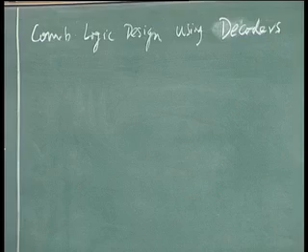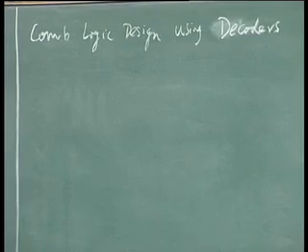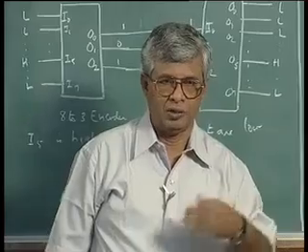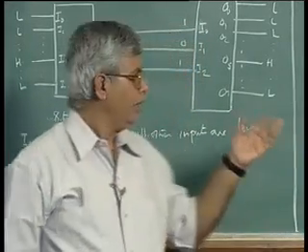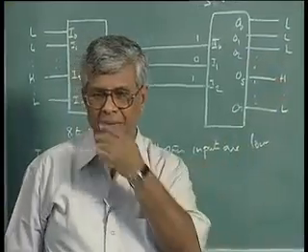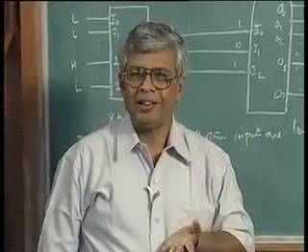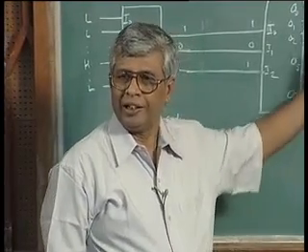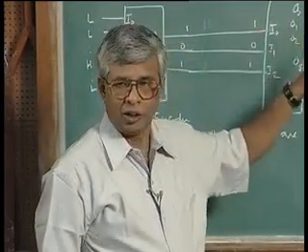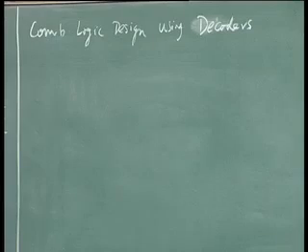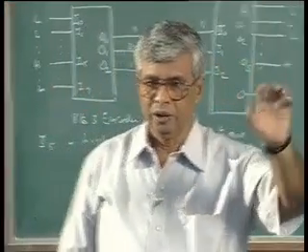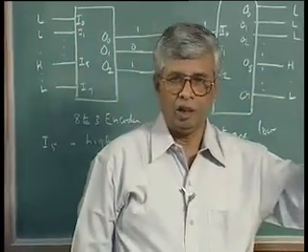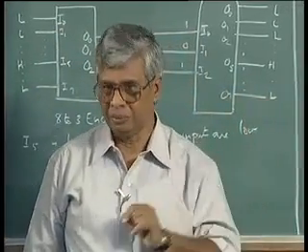This is a very straightforward procedure here, because with the multiplexer of course the mapping procedure was very clear, but not even that here, it is a straightforward case, because when you have 3 inputs and 8 possibilities, this is similar to the truth table, is it not? So that means all possible minterms are generated. The question is, one of them will be high, all others are low, but in general, when you have 3 inputs and 8 outputs, it is equivalent to a truth table with 3 inputs and 8 outputs, each of these outputs being a minterm.